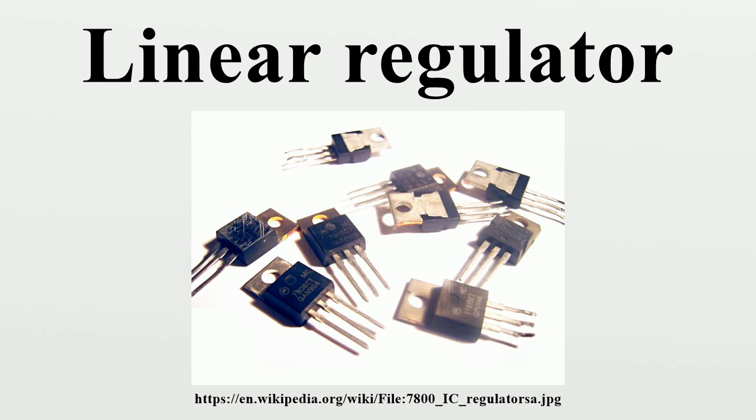This circuit has much better regulation than the simple shunt regulator, since the base current of the transistor forms a very light load on the Zener, thereby minimizing variation in Zener voltage due to variation in the load. Note that the output voltage will always be about 0.65 V less than the Zener due to the transistor's VBE drop. Although this circuit has good regulation, it is still sensitive to the load and supply variation. This can be resolved by incorporating negative feedback circuitry into it.